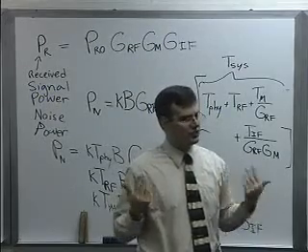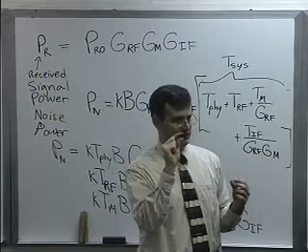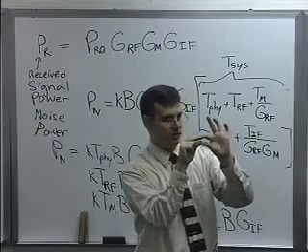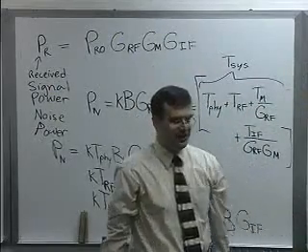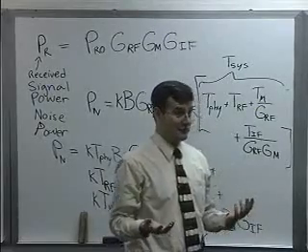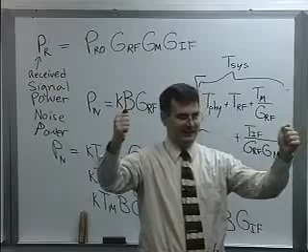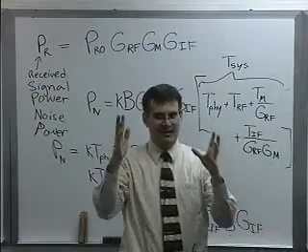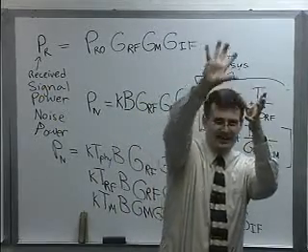And it's just a sort of semantics. The way that they define that noise figure, or that amount of noise, is with a temperature as measured at the port. So sort of the gain is all kind of included in there. If you think about it, if you didn't do that, the problem would become very hairy, right? Because it depends on where you point your antenna, and you've kind of got to integrate over the whole pattern, right? It's like if the main beam sees a hot spot, you got to take that gain and weight it against the hot spot.